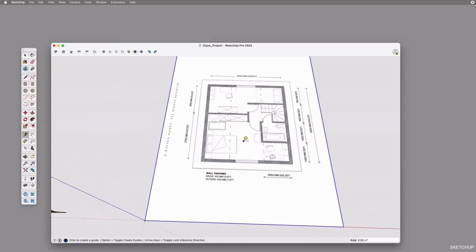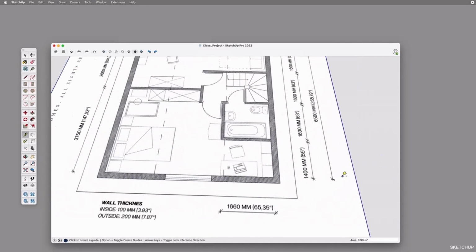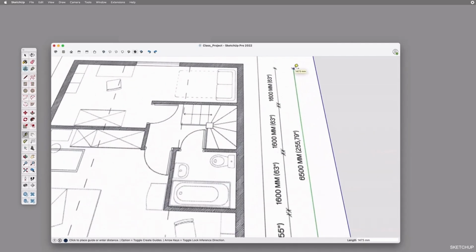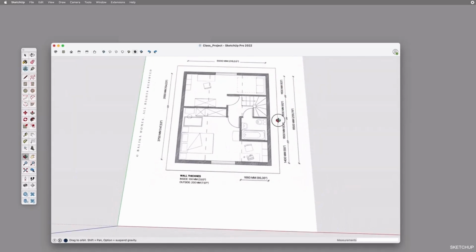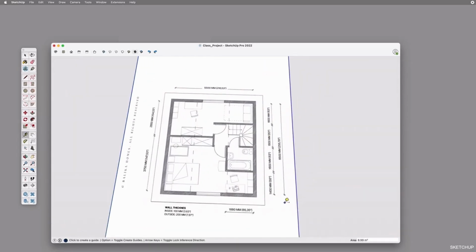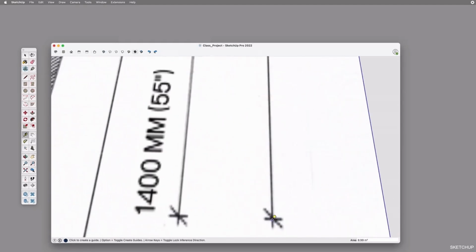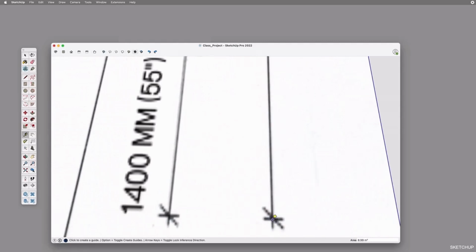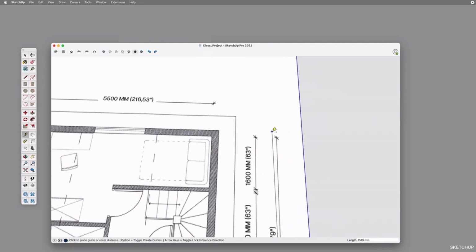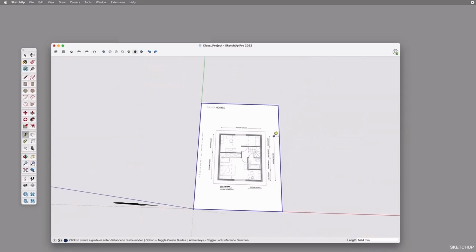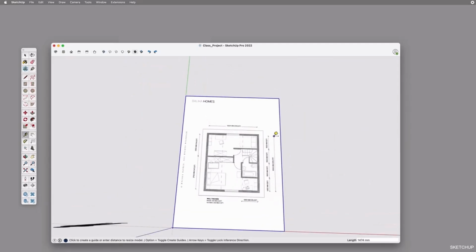When I use my tape measure tool now and recheck the length of the measure, you will see that it's not big enough, so we need to scale it. So while we have the plan selected, I'm gonna use the tape measure again, and I fixate the measure by clicking once at the beginning and clicking another time at the end, until we see the measure appearing on the right bottom corner.